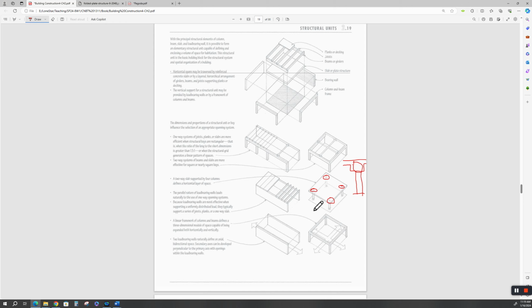In the same way with the footing, we have footings go down here. If that was resting on just a thin slab on grade, that would be bad. In actuality, that column would probably go through the slab on grade and have either a bell or a square footing. Okay, enough of that.